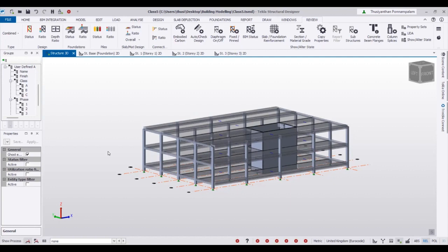So wind loads you have to calculate based on EC1. Based on EC1, there's a formula to calculate the wind load. Normally what you want to calculate is the wind pressure, right? Pressure varies throughout the height. Okay, there are some rules of thumb that I am going to use because these are low-rise buildings.